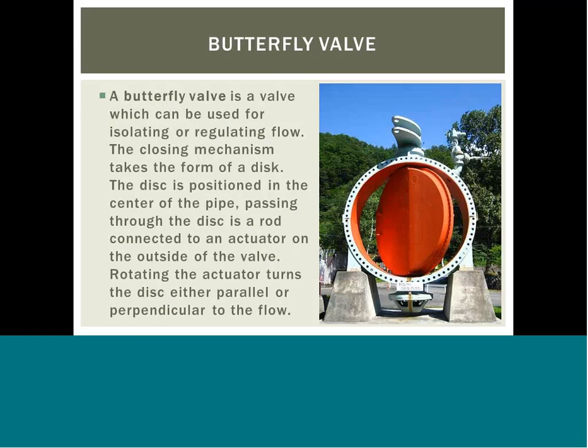Operation of a butterfly valve is similar to that of a ball valve, which allows for quick shutoff. Butterfly valves are generally favored because they are lower in cost to other valve designs, as well as being lighter in weight, meaning less support is required. Unlike a ball valve, the disc is always present within the flow. Therefore, a pressure drop is always induced in the flow, regardless of valve position.